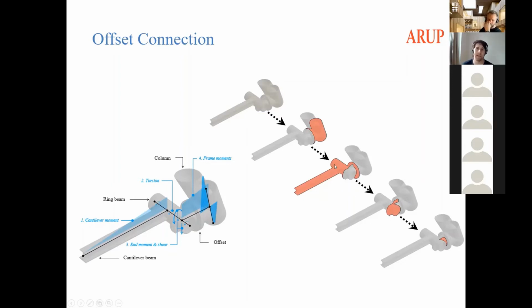And finally, we have the cantilevers here, which are all HE sections. And in order to create this idea of architectural mythology that Tu mentioned before of a floating ramp, we needed to have a maximum height of the I-beams of 200 millimeters. And why this is especially interesting, we can see if we start looking a bit at how